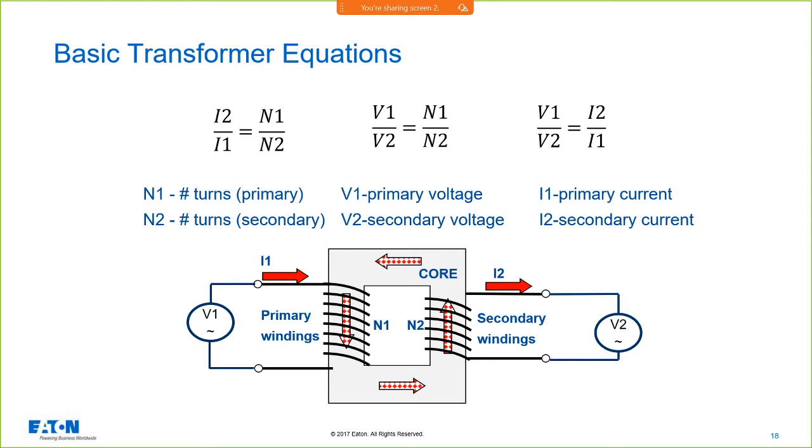Now, understanding that applying a voltage on the primary, it will induce that voltage on the secondary and it'll drive the load, whatever that load is that's connected. If I don't connect the load, I'm not going to be pushing current to nowhere. It will deliver the kVA, it'll deliver more than the kVA. You've got to be careful about overloading a transformer, but it will deliver the demand that's placed on it.